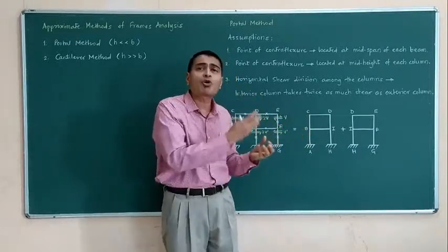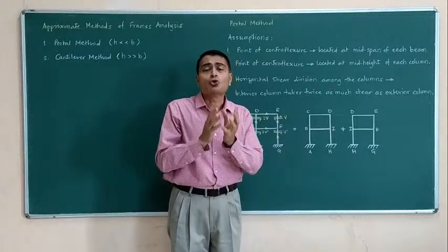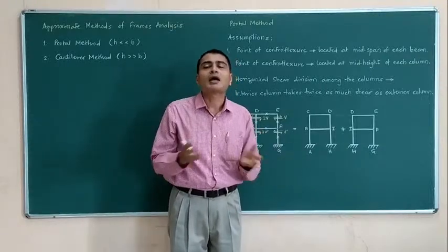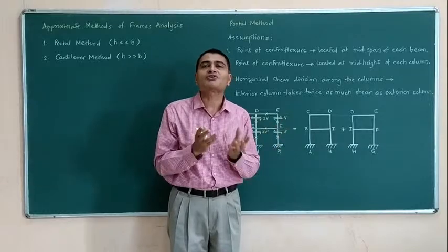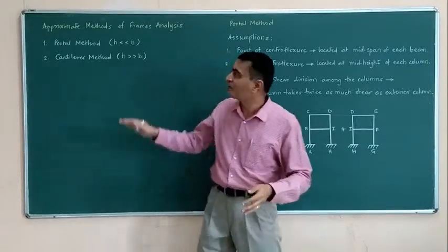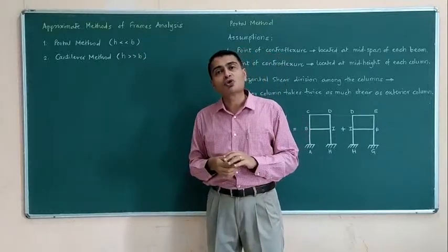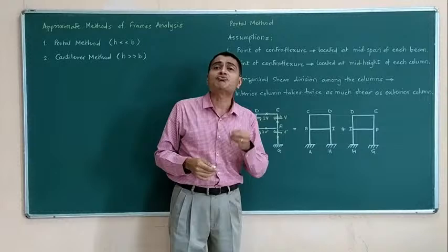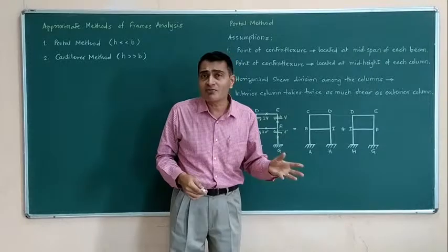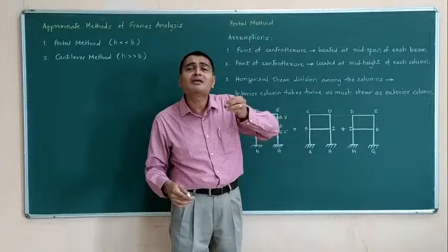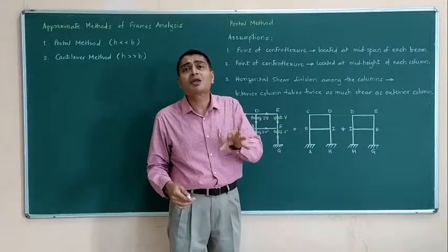You develop n number of FBDs, you apply sigma M, sigma Fx, sigma Fy, and you get all your shear forces and moments. It is so simple. That is why these methods have become popular, because with the help of these assumptions, analysis becomes very quick, very simple, and the results are acceptable, with an acceptable amount of error.